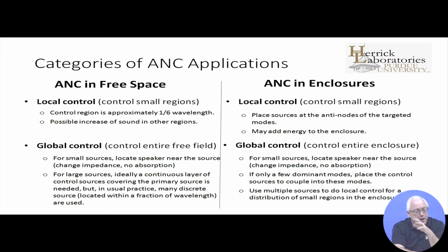So whether that is possible or not is a good question. We've done things with, if you also take a look at multipole expansions of monopoles, quote unquote, you can represent a monopole source with a multipole that's displaced some distance from it, and we have demonstrated that you can achieve significant control over global regions with that, in a region that excludes a sphere, including the primary and secondary sources. So you can sort of do these things, but the degree of complexity gets pretty high pretty quickly as you move up in frequency.